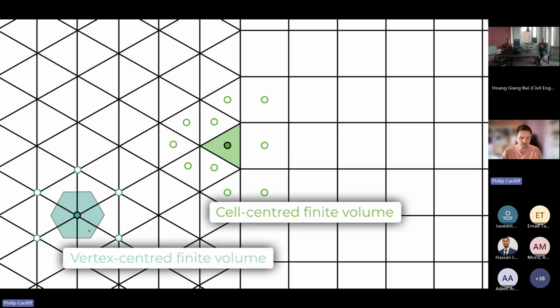It's not the standard, but I've worked on that as well. It's exactly the same idea, except you store the solutions at the vertices, and then you form integration volumes using this dual mesh. In contrast, in finite element you normally derive it based on the elements, but in effect you're doing a conservation for a center node over an integration volume, which is the adjacent elements. The computational stencil in that case is like the boundary. So it'll be the same as a vertex-centered method, but the integration volume is different.